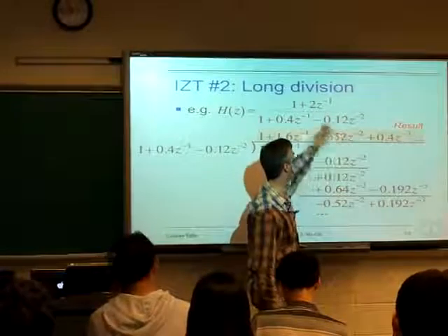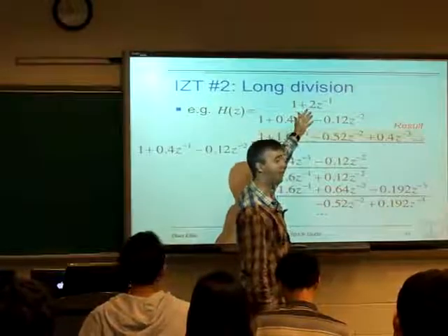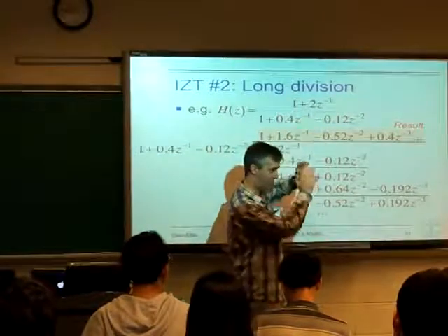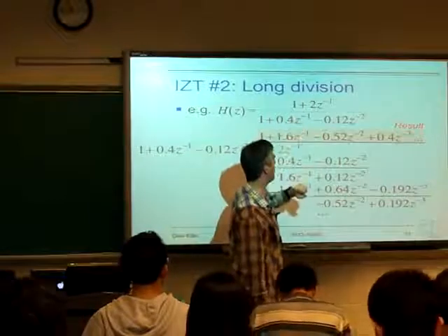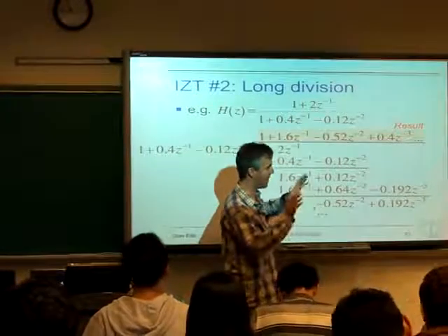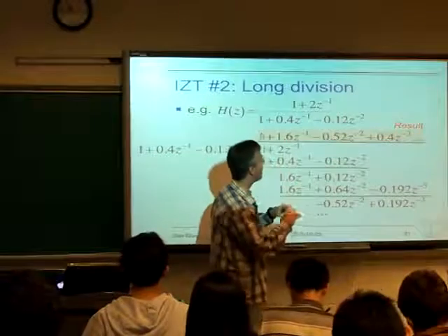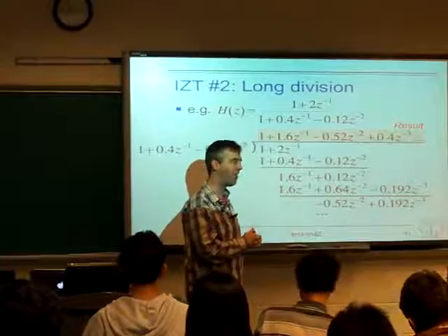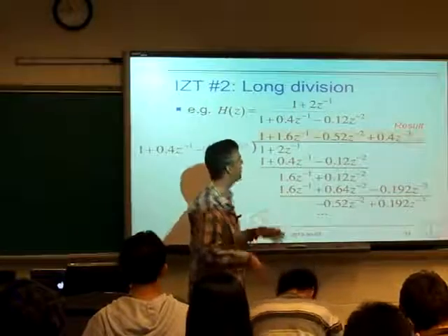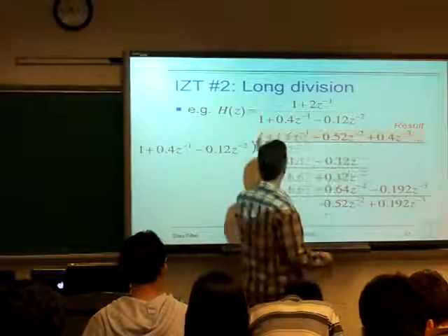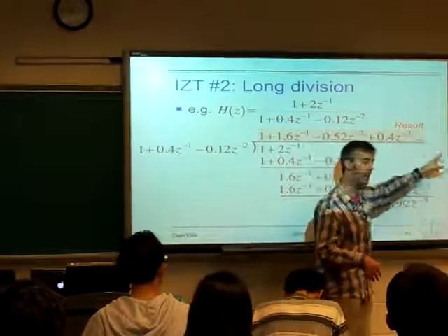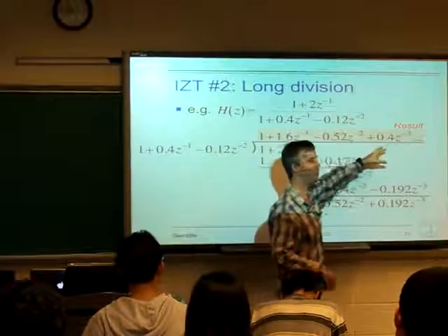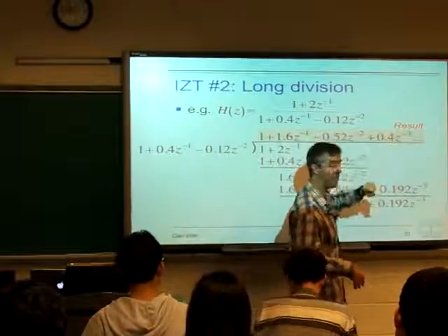If someone gives you this and says, what is the value of h of 3, little h of n for n equal 3, that this Z transform corresponds to, as long as they gave you the region of convergence. So they tell you the region of convergence, and you'd say, oh, okay, it's the outside of some circle, therefore we're talking about the right-sided version. And then you know that you're looking for a solution like this that starts at some power and then goes into increasing negative powers. As long as you did that, you could then just do this up to whatever value you wanted, and then you'd have the value you needed.